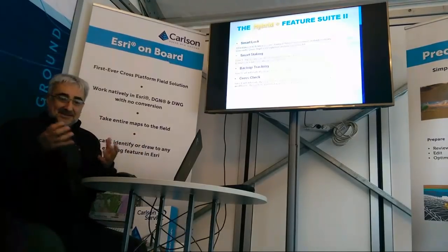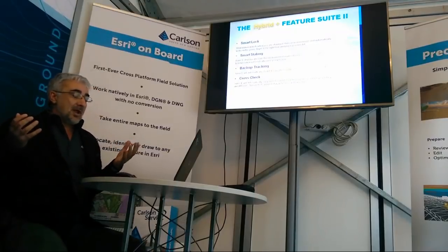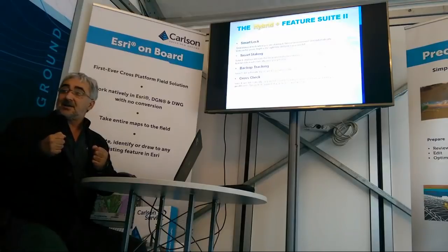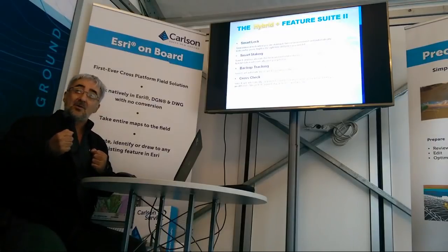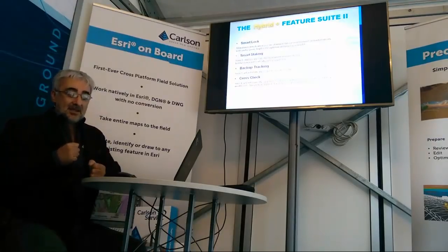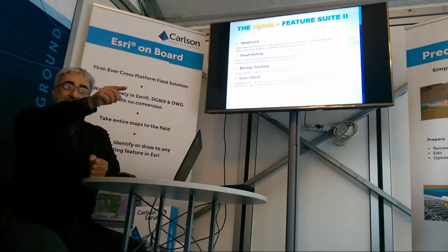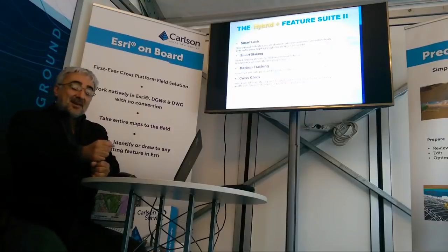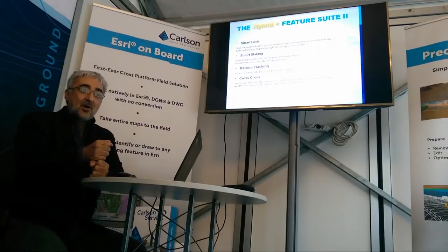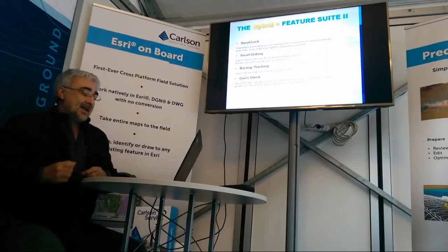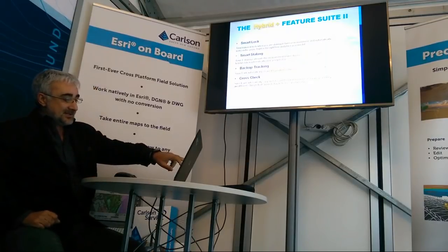You still see the position. When the search detects you're slowing down, that means, well, this guy wants to measure. So when you're slowing down, it turns to your position, tries to lock the prism, and then when you're leveling, normally you are locked to take the robotic shot. Fine. It's a bit different in staking.